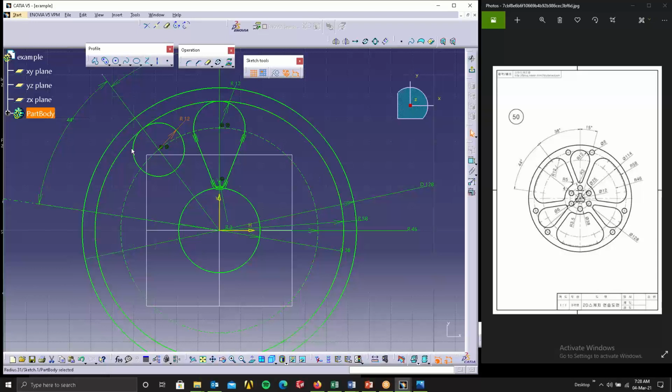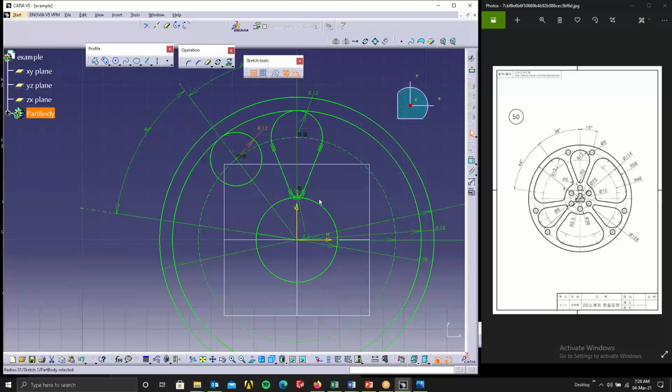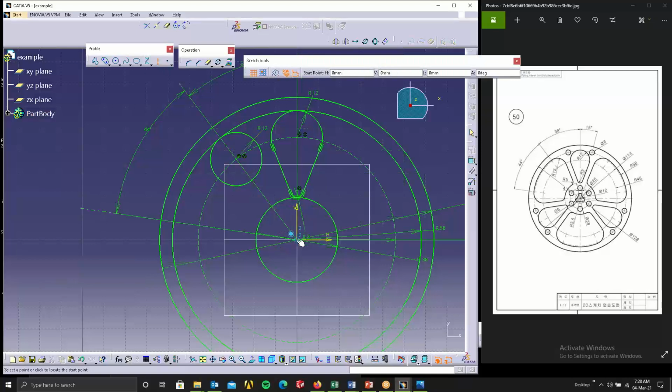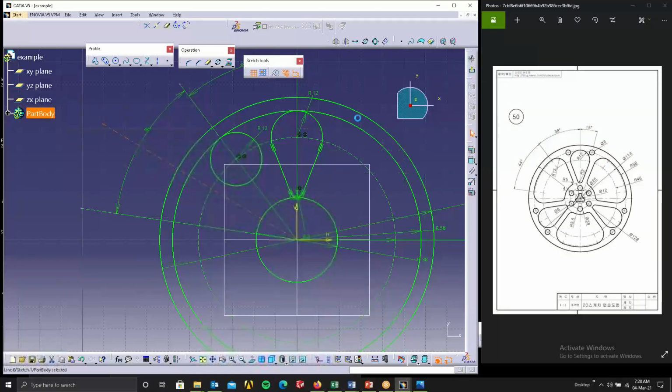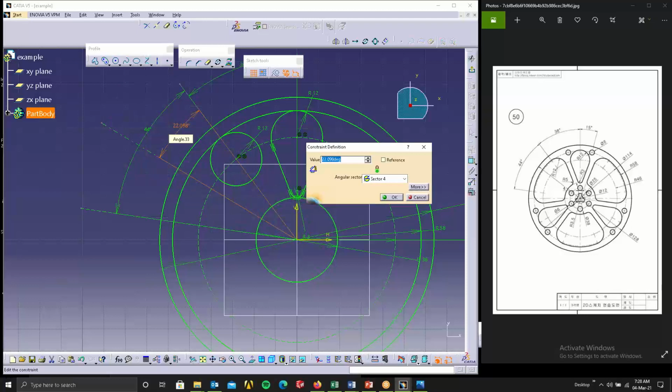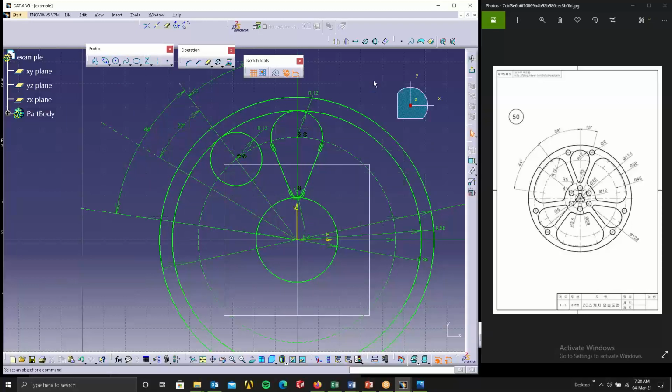It's touching here. Okay, that's correct. So now what I can do is, okay, I'll take reference from here. This I'll make 22 degrees. I make this 22, enter. Okay, now here what do we have? Here we have radius 5 at certain location over here.